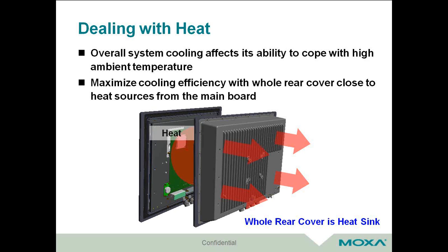You see these robust housing structures for these complete self-standing HMIs or panel PCs that don't have to be embedded in, I guess you would say, a dashboard or control dashboard. They look like they're just built to endure rain and abrasion and things of that nature, but actually it's more intelligent than that. You see those fanless designs in the back, those metal fins in the back. They're vertical for a reason, and the width of the metal is a certain width for a reason, and the placement of the internal components is there for a reason, and it has to do with heat dissipation, convection in other words.